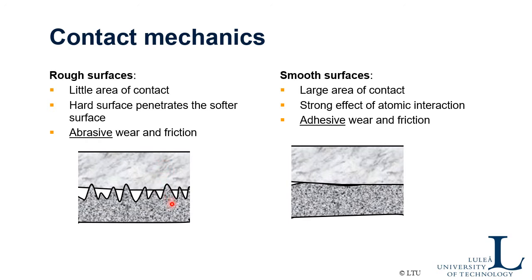And when you then slide the lower surface relative to the upper surface, you will abrasively wear off material on the surface. You will plastically deform it, you will plow it or cut it away. So that's a kind of abrasive wear process, as well as it also becomes an abrasive friction process.